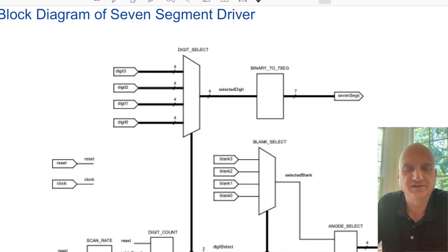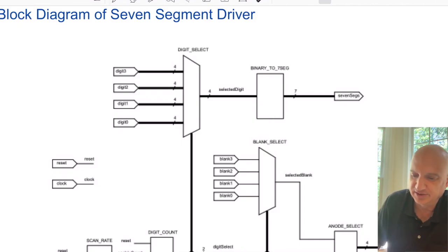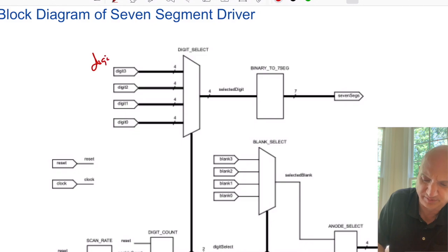They just care about displaying their numbers. And so since these digits typically display values between 0 and, if you're into hex, up to F, or 0 to 9 if you're just doing a standard decimal display, we can use 4 bits, and those 4 bits will represent a value on the input. This could be, I'll rewrite this since they're not showing up great, digit 3, and this is digit 0, and this is digit 1, and then this is digit 2.